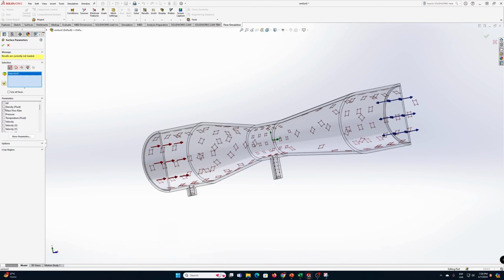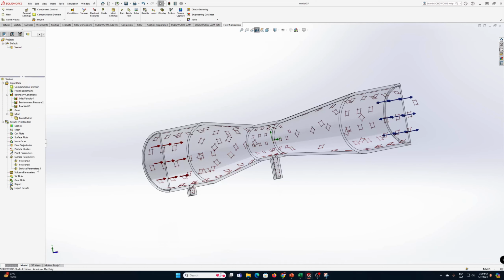And finally, I want a third one that will be this option for this section. Select other, imported. We already set the value of the velocity, but we want the value of the volume flow rate. So instead of calculating the volume by hand, you ask the software to give you the volume flow rate in this section. I will select the volume flow rate in this section that represents the inlet. And here we change the name, volume flow.